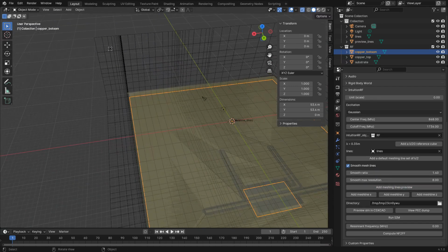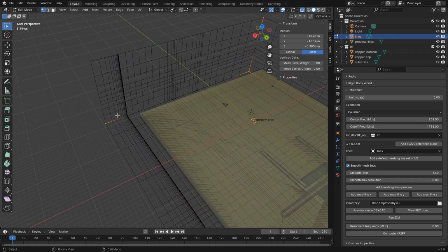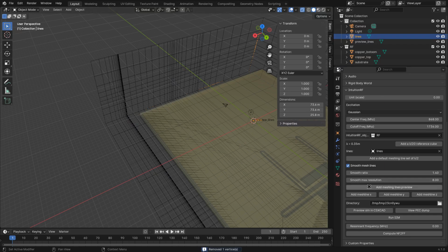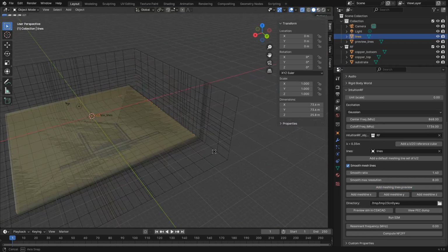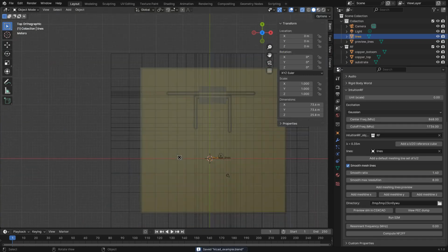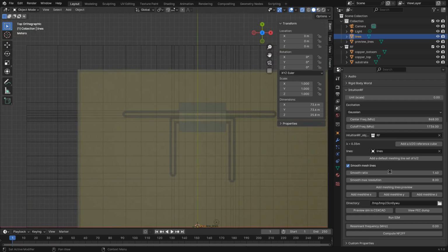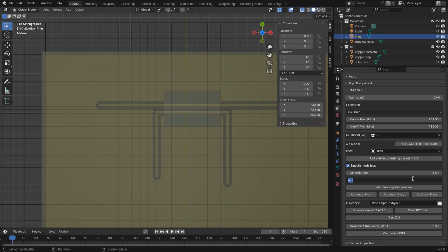Now what you see here means that you have two vertices that are overlapping. So let's fix this. And now if we merge by distance and mesh again, as you see, it fixed it. Okay. So let's now make it finer like this. So this is already quite good.